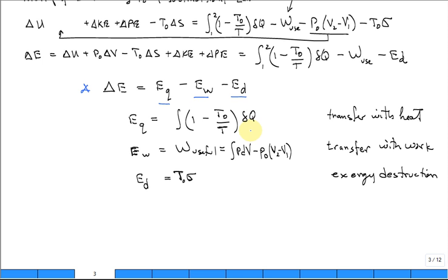So this is the equation for the transfer of the exergy with the heat. What is inside this parenthesis? 1 minus the low temperature T naught, the dead state temperature, divided by, conceptually, the higher temperature, the temperature at which the heat is being transferred across the boundary of the system. Sometimes I'll put a T_B right there. What is in that parenthesis right there? What is that? 1 minus T low over T high? Carnot efficiency. That's exactly what it is.